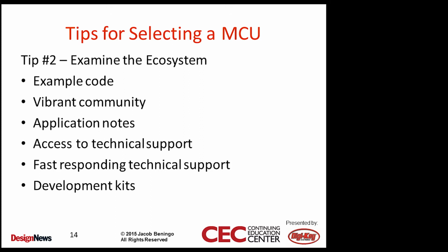I've worked on a couple of projects where the electrical engineers designed the product up front, so they had the hardware ready. They selected the microcontroller. They never checked to see if there was an ecosystem, if it was supported. It turned out the microcontroller actually wasn't in production. It was very hard to even get microcontrollers, and there were no application notes. There was no technical support or anything.